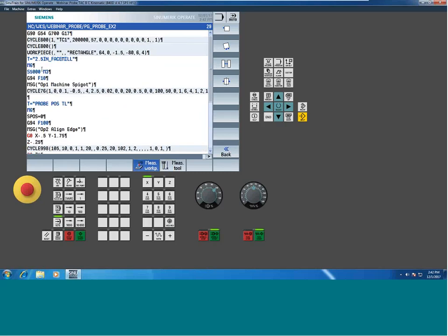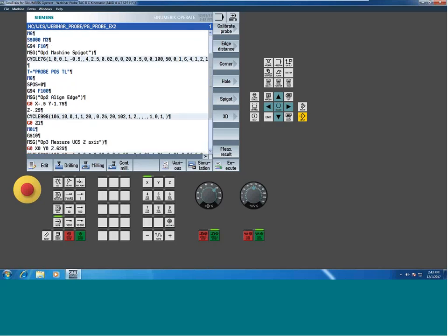Now when I did the first machining, I'm machining at G54. So I machine the part at G54 and then I measure into 510. The G54 doesn't get adjusted or changed in this scenario. You can use the same work coordinate if you wanted to. So what is the result going to look like? Let's look at it in a few stages. If you notice, I put a couple of stop points in for us with some optional stops.